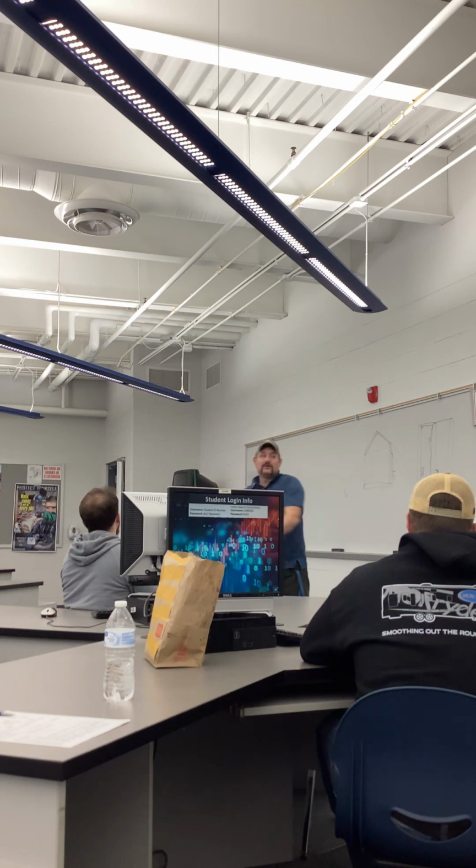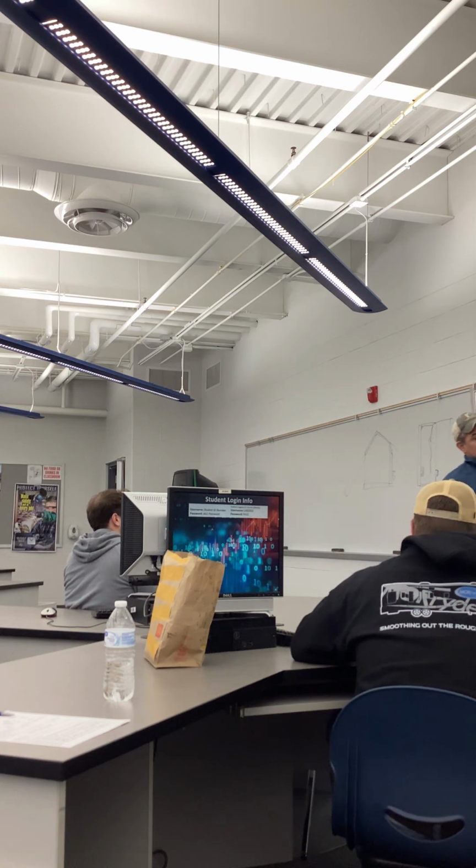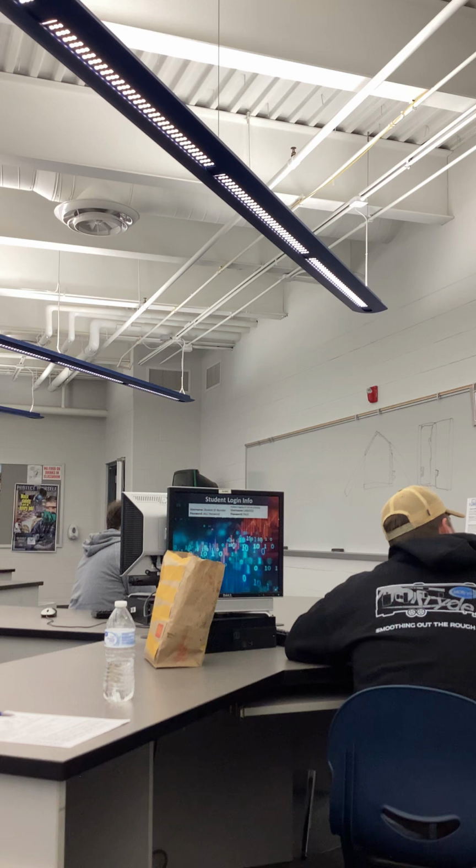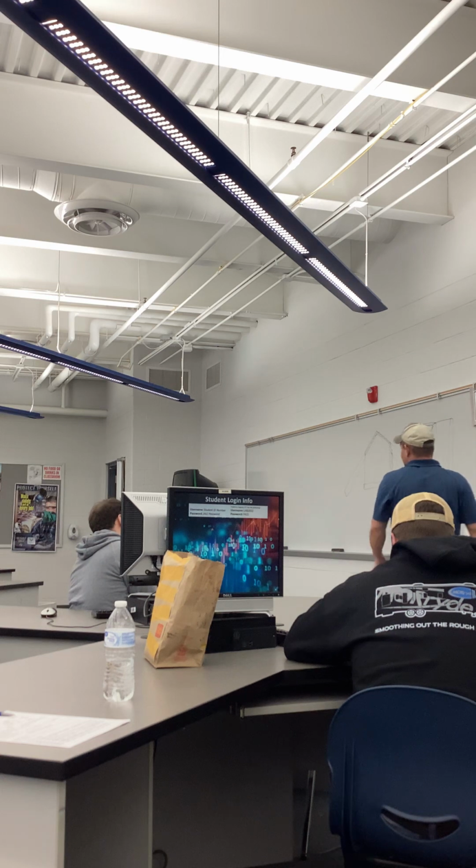Makes sense? So, thermal and air infiltration, exfiltration, and insulation all go together. Heat transfer. When we're building, and we're going to get into this a lot more in the green, you see this here? See this pipe? See that hole around the pipe? Those are the leading causes of infiltration. When we drill through the floor, or into the attic, we have to put a pipe through into the attic, and we don't seal that pipe. That's the leading cause of air infiltration.